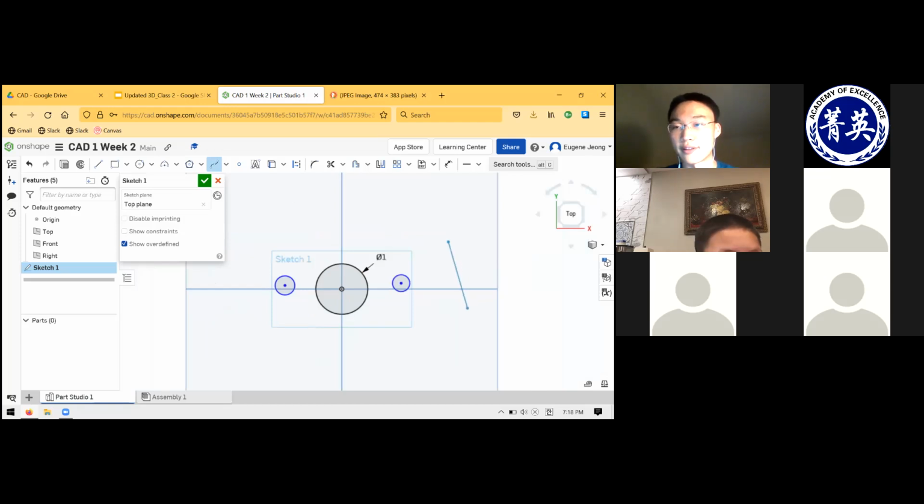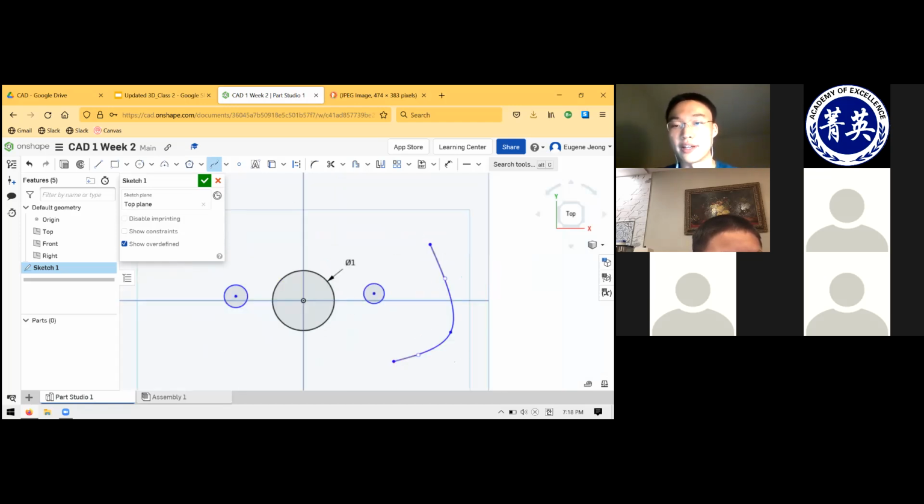Depends on the CAD program, but I think the Onshape ones, let's see. Just creating a 3-point spline already creates 5 different parameters that I can edit. So the best use for splines, from what I've experienced, is when you really don't care about fully constraining your sketch, maybe you're just doing some freeform tracing of a shape. In that case, maybe it's okay to use a spline.